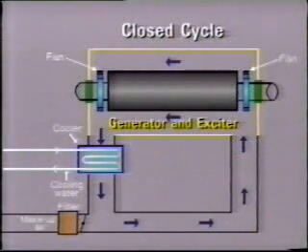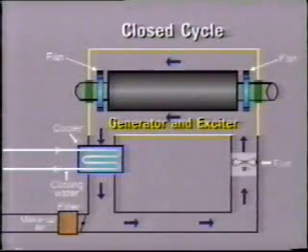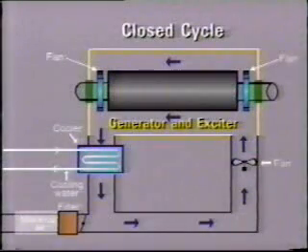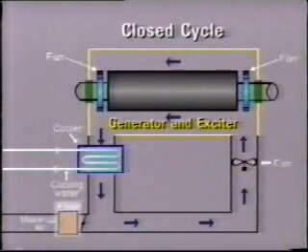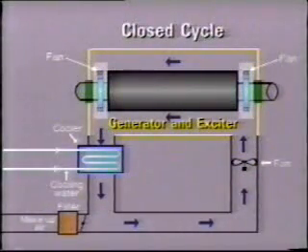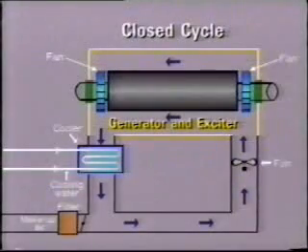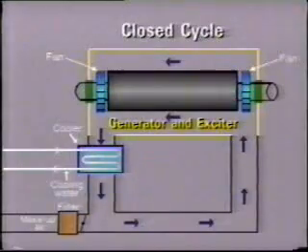Because of the additional pressure drop across the heat exchanger, it may be necessary in some generators to add a circulating air fan. Make-up air to compensate for any leakage is admitted into the suction of the circulating fan. Filters are provided on the make-up air inlet from atmosphere. In other designs, the shaft-driven fans are made larger so as to avoid the need for a separate air circulation fan. With this arrangement, make-up air is drawn in by the fan suction through the generator housing.